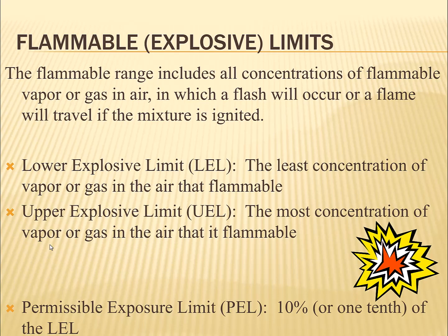But still, just generally speaking, when we're talking about flammable liquids and therefore flammable vapors over time as it evaporates, you need a certain concentration, depending on the substance, depending on the gas, for it to be explosive, for it to ignite in the air. And we call that minimum concentration the lower explosive limit, or LEL.